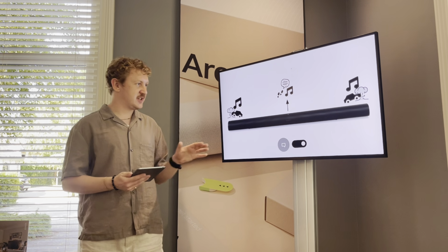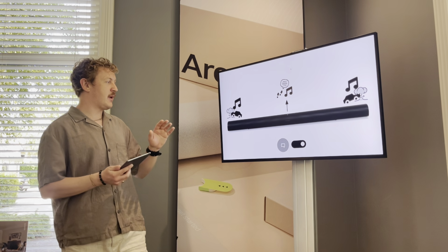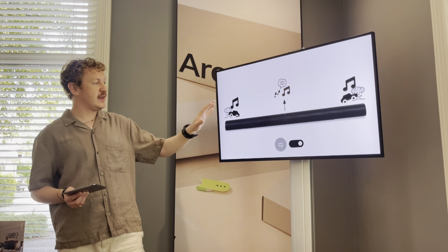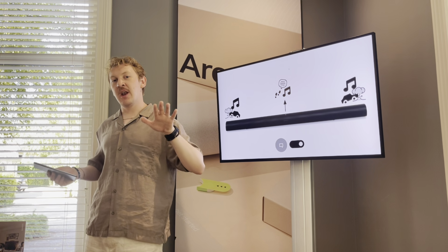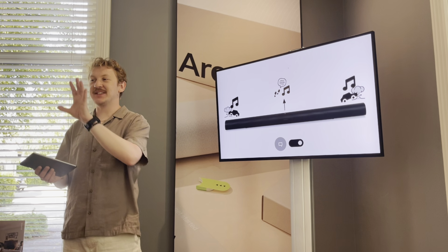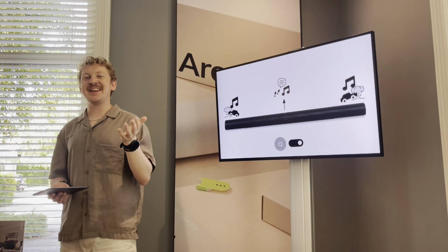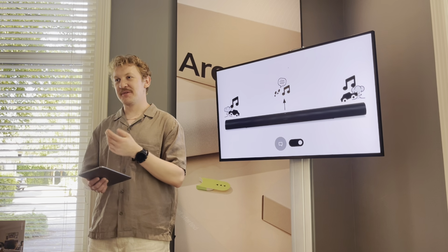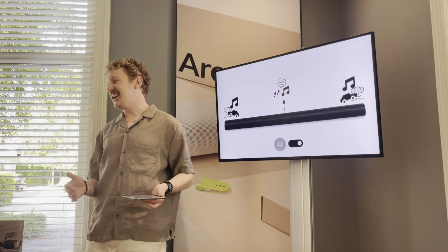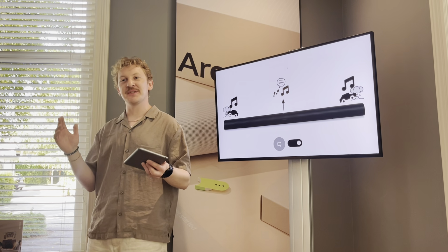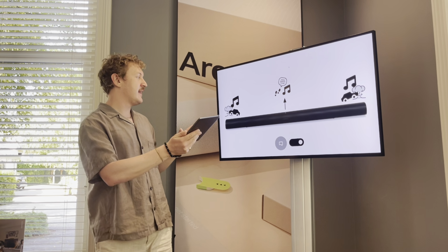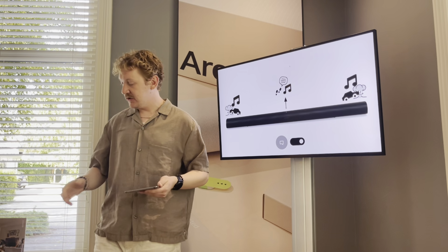And just as a side note, when we were first initially testing this feature, we experimented with leaving the centre channel where it was, but lowering all of the other channels. We were thinking that could clear up the centre channel slightly. But then if you play any non-dialogue scene through that processing, it just loses all impact. Any action scenes, any car chases, music montages, that kind of thing, completely loses its power and its punch. So really, we had to look at another solution.